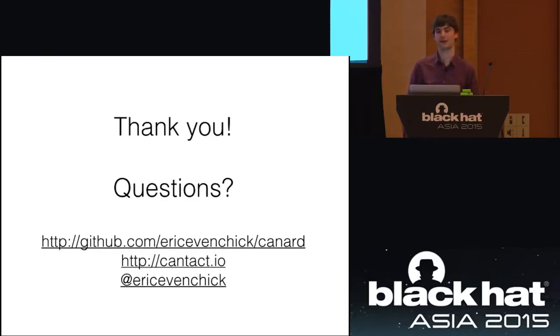Okay, the question was, how could you brick a car? Apparently, Charlie Miller managed to brick his car and posted about it on Twitter. I'd say one of the biggest things is if it's a car that does have writable flash for firmware. Obviously, if you write some junk firmware to a controller, it's probably not going to end well. Other things you could do: if you start messing around with VIN numbers, cars often have checks to make sure that all the VIN numbers and controllers match. So if you start playing around with that, you could potentially stop a car from starting.